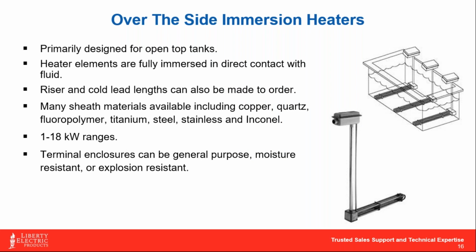An over-the-side immersion heater is exactly what it sounds like. I think we found a couple of pretty good graphics to put in with this slide as well. We don't see quite as many of these as we used to when we had a much more robust industrial segment. This is a product that is used pretty much specifically for open top tanks, and they're popular in plating operations, or places where you've got chemical dip tanks.